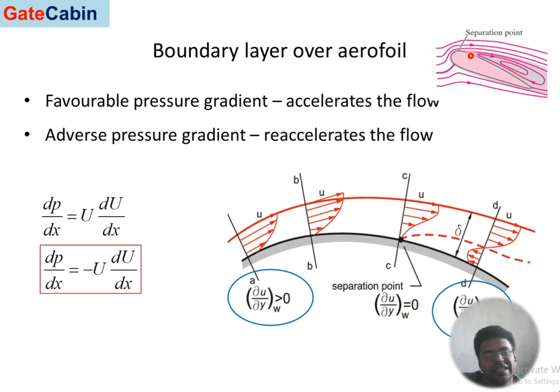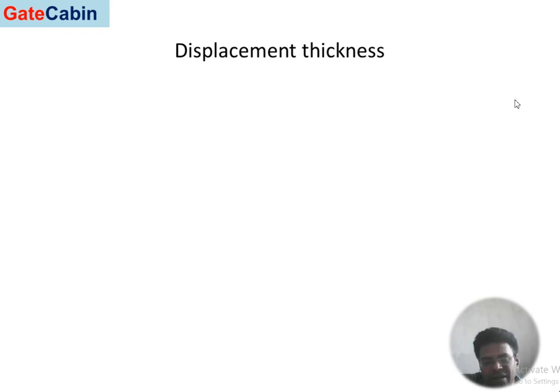So these separation bubbles sometimes start from the leading edge at high velocities, and sometimes start from the trailing edge because of the flow acceleration and inertial effects, and they occur at high angles of attack and or at high speeds, high velocities. This flow tries to remove or detach the upcoming flow, and results in flow separation with a heavy loss in lift and then an increase in drag of the aerofoil surface.